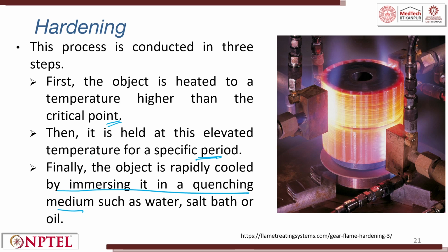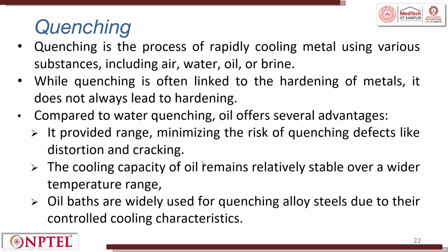Something like nitriding, where you can have nitrogen passing through it. So, you can also have water, salt or oil and gases also. So, hardening is a process which is very important. Here it is held at a certain temperature for a certain period of time and then rapidly cooled.